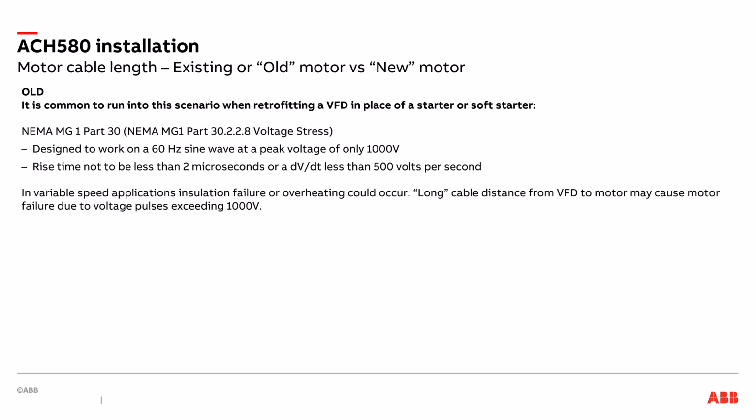In these cases, they are not inverter duty rated motors, so it's very important to account for the cable distance that's associated with the distance between the drive and the motor. In these applications, if you don't take account of this, you're exposed to insulation failure or overheating.